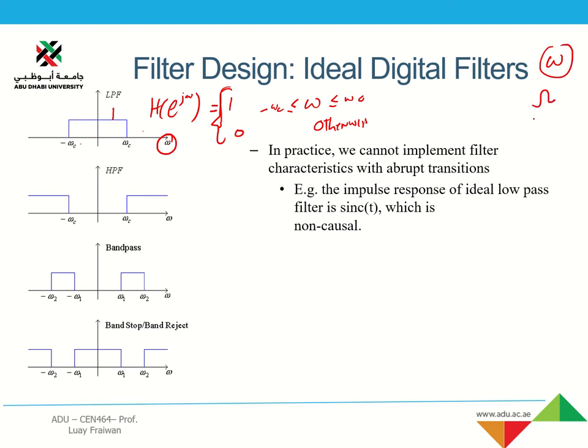If you remember the impulse invariance, that is how we can convert between digital and analog. Digital is basically a sampled version of the analog or continuous time signal. So this is a typical low pass filter. If you remember the last chapter when we studied sampling, we found that the impulse response of the low pass filter is written as omega c over pi times sinc of n times omega c.